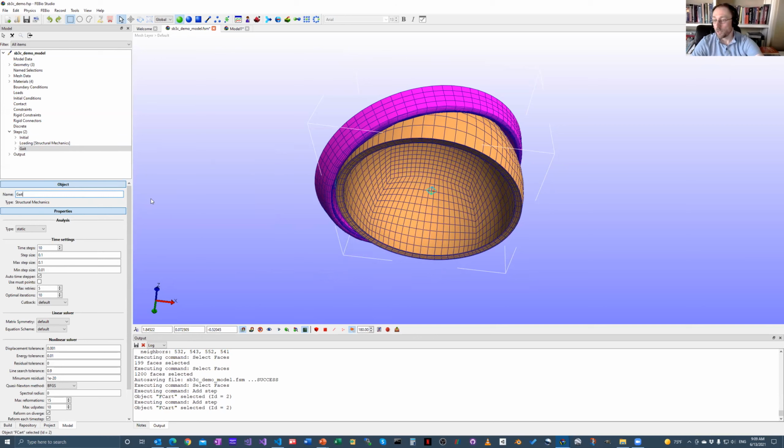So there's a question here regarding the remesh. Is it possible to constrain the remesh to preserve sharp edges? The answer is yes. So the MMG tool, which is a third-party tool that we're now using in FEBio, does a really good job in preserving sharp edges. It has its own algorithm that it uses to detect sharp edges in the model, and you have some parameters to control that, but it will preserve any sharp edges that it encounters.